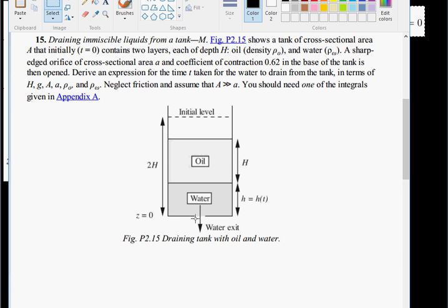And then we're draining through this orifice right here, and it's a sharp-edged orifice, so we are going to get the vena contracta effect, where the lateral momentum of the water draining, following a streamline like this, will cause the contraction of the outlet stream, so that you'll have a narrower cross-sectional area right about here before the water starts flowing straight down perpendicular to the bottom surface here.